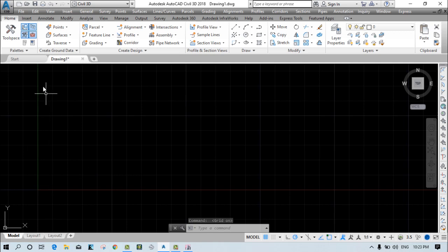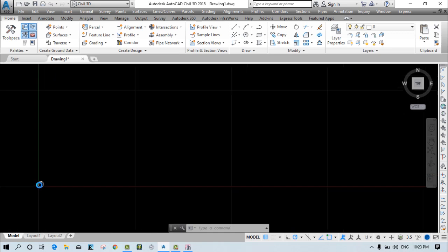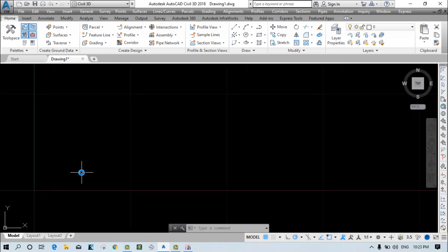Now you can see this is the y direction and this is the x direction. This particular point is very important for you because this point will help you identify the location of your plan. Your plan location should be very near to the origin of the Cartesian system. Why? Because it helps you take all the dimensions properly and provide all the plans properly. When we proceed to design, it will definitely reflect in all the patterns. So that is a very important parameter.